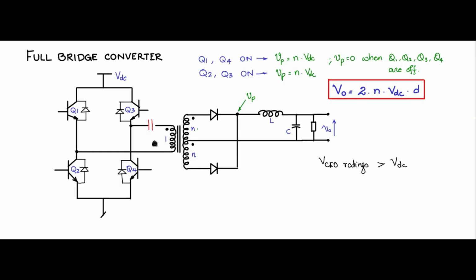Now, in the case of the full bridge converter also, we see that there is a requirement for solving the flux walking problem. Wherever this kind of a situation occurs where you are having switches and practical or non-ideal switches, and you are having a winding connected in this fashion, there is a chance of an average voltage occurring across the V primary.